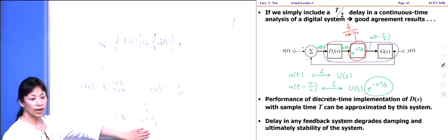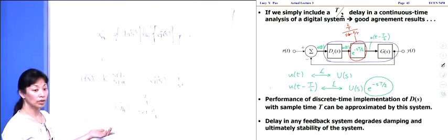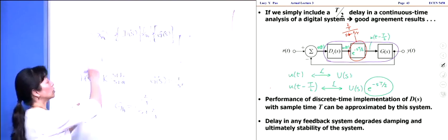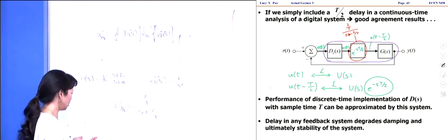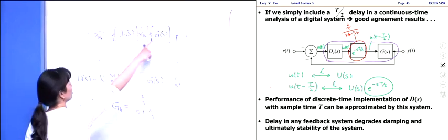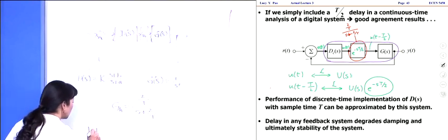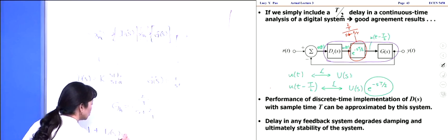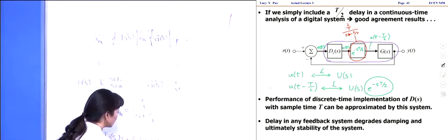And a question that I ask in the added problem 3.1c is plot the root locus of the closed loop poles as a function of cap T. And a question then that arose is, well, how do we do that? Right, so ultimately, your closed loop poles of this entire system are governed by 1 plus D of S, GH of S, times G of S is equal to 0.